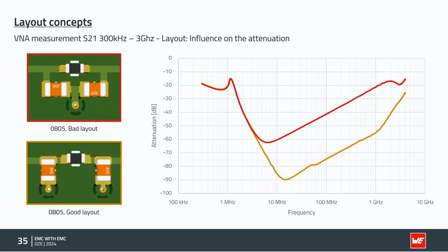So what happens? First of all, we have some small parts of our transmission line going down to the components. This is an inductance. One via is an inductance. So some noise is going to go this way, and some parts will say, no, that's way too high for me, I will go the straight way to wherever that's going to be.